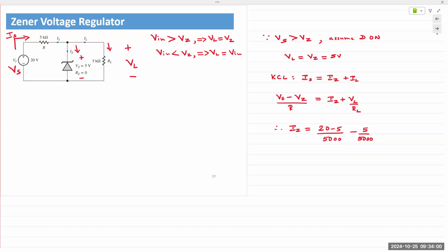Point being made in the class is that the Arduino, can we power the Arduino with a 12-volt source? Now, is the 12-volt source a battery or is it from a power outlet? 12-volt DC coming from a source. And can we connect a 5-volt Zener at its output and power the Arduino with that?